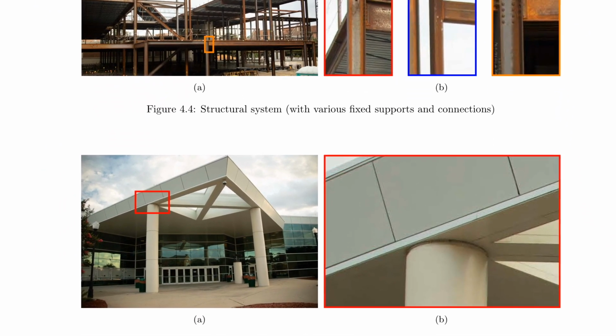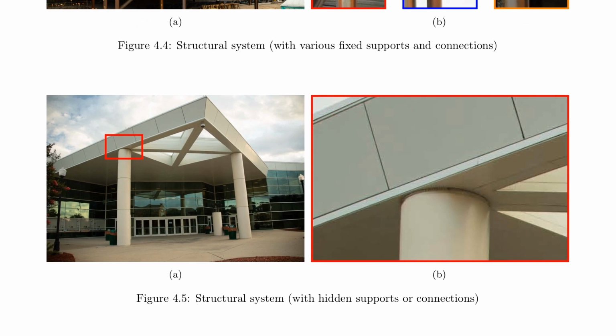Let's take a look at one other famous structure here on campus. And this one here actually also has a connection up here, but in this case, we can only guess because it's behind the building cladding. However, you can see a beam here that is supported, and you can actually see something that is supported here as well. And it also helps to support the roof from here to here. So it's an entire structural system, but that structural system definitely has a connection and a support reaction up here for this roof. My best guess, and I cannot see inside, is that it's also a fixed connection, but we really would have to go and dig into it to see what's going on.